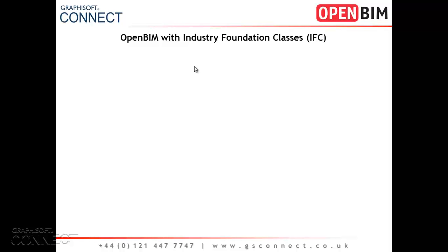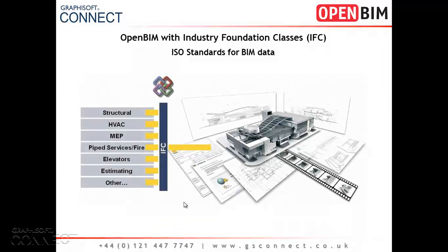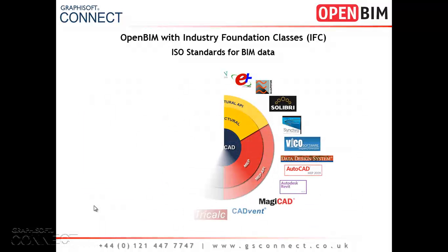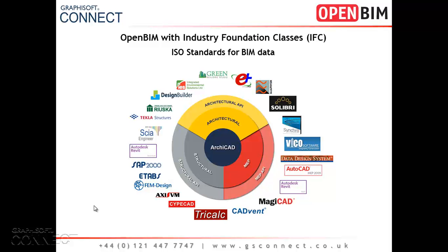To explain a little bit more about IFCs, these are actually Industry Foundation Classes, and effectively this is an ISO standard for BIM data. What IFCs allow us to do is take a typical model from ArchiCAD, such as this one, and then export using the IFC standards to various other disciplines to enable them to interact and communicate with other users and other disciplines. This little graphic gives a sample of some of the different types of software in the different fields that have easy access to the IFC communication links.